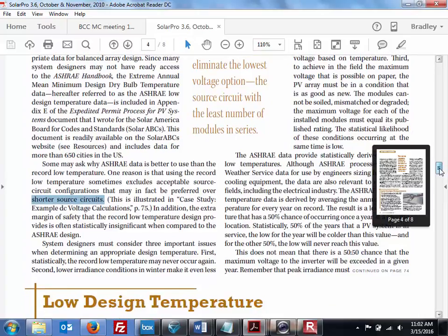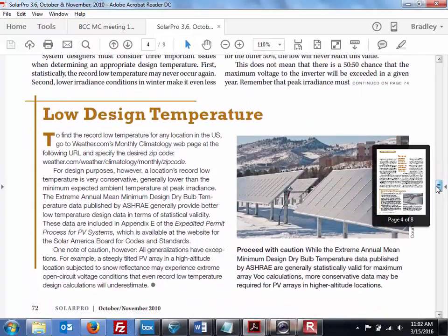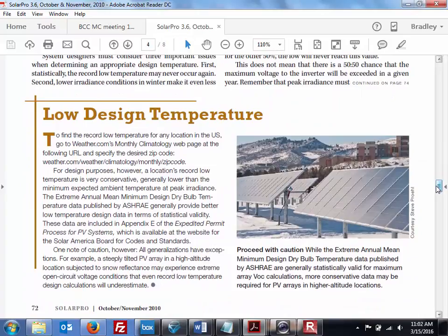Okay. So how far does it really start to limit? Yeah, we haven't done them yet, but for every wire gauge, resistance is measured in ohm centimeters, and so the length will tell you how many ohms you're going to lose, and then you run that through your P equals I squared R, and that'll tell you how much power is being lost. Every single wire has that. But we'll get to that. That's coming later in the course.